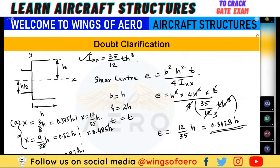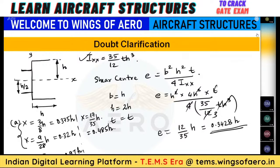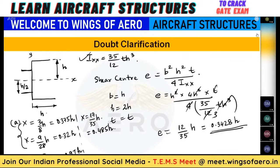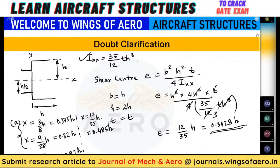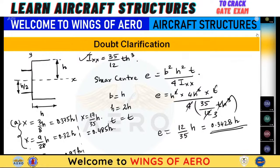So we know in this C section it will locate somewhere in the X direction, and it should be outside, isn't it? So somewhere here it will locate. Now if I have the two options, 0.32 and 0.375, you have to use some kind of reasoning to find out this answer.